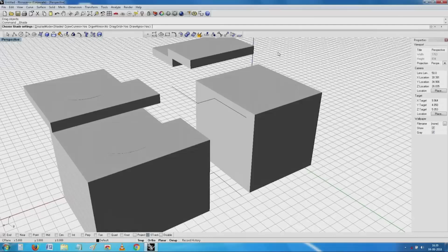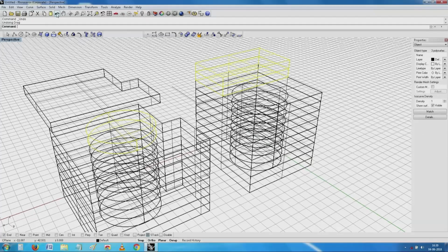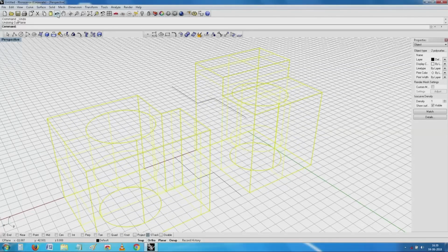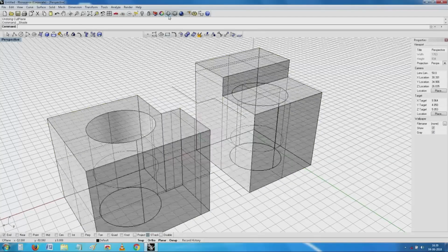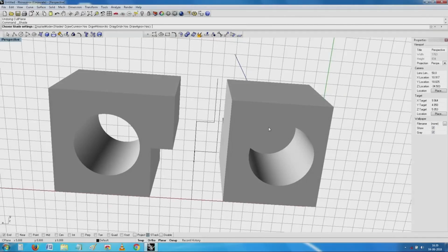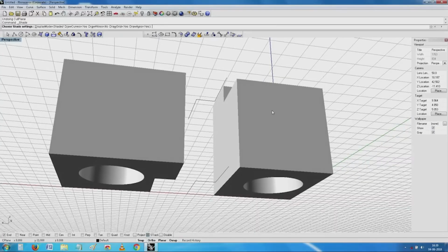but what I wanted to actually tell you is that it is very much possible for us to check the orientation of the object and see how putting it in one particular direction. It is obvious here, is it not? So, this starts building without any support required, and the top layer may need a support. So, you need to take a call once again, because it is circular, there is nothing, only that middle layer we may require something. So, you now decide where to cut it and how to make join things.